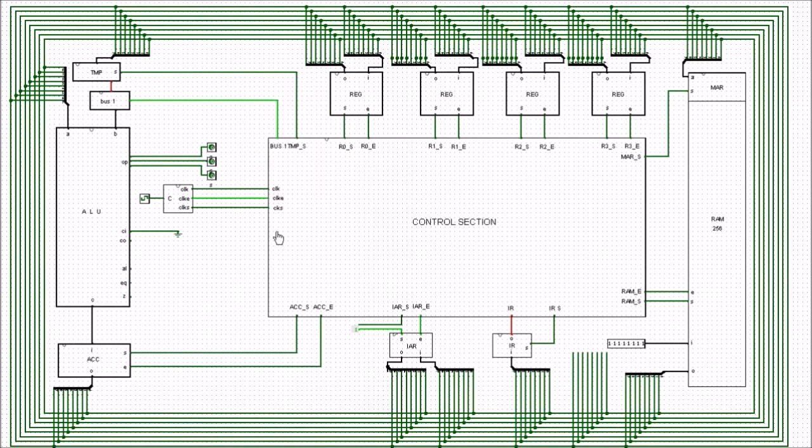Now the reason for doing that is that we're in effect getting ahead of the game here, because we know that the instruction address here is just a value of 0. We know that the next one will be a value of 1, and the one after that will be a value of 2 and 3 and 4. So what we're doing is we're getting a value of 1, which in effect is our next address for our instruction, and we're putting it into this ALU here.